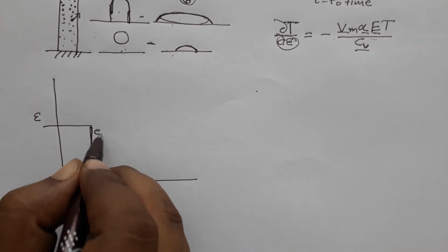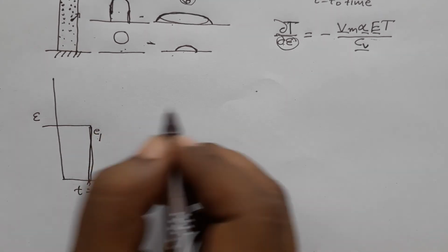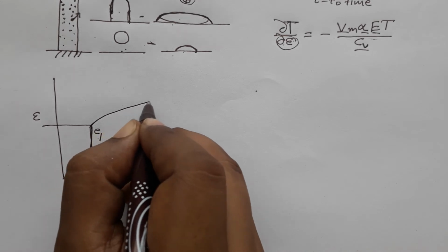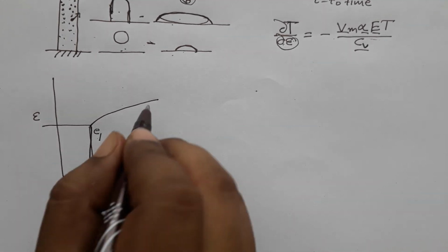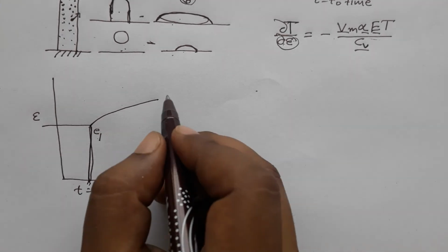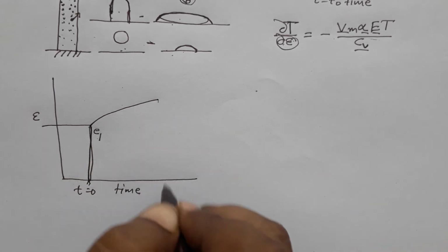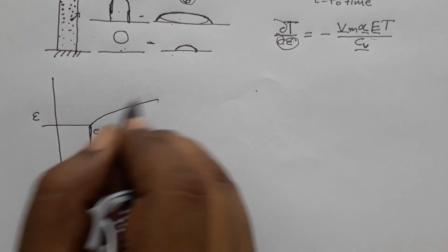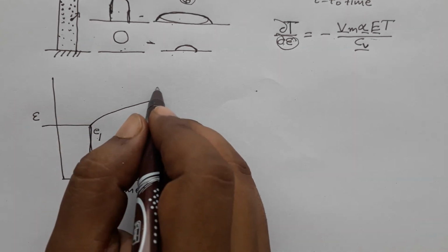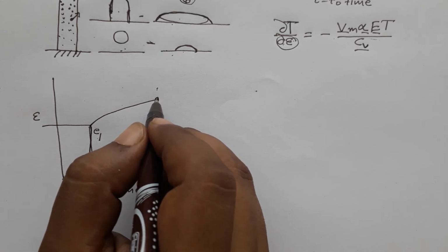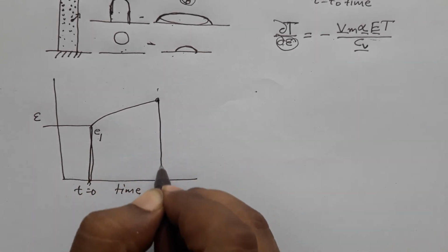So, that is E1, and then you allow it some time, and in that time the strain will increase following some behavior. It could be linear, it could be non-linear. So, it will increase to the isothermal point. So, the atoms have found their new configuration, and it has reached here at, let us say, time equal to T1.